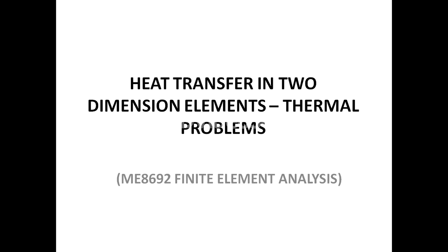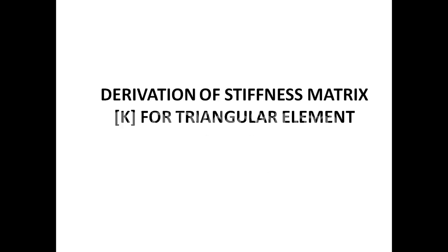Hi. In the previous video, we discussed the derivation of the shape function related to heat transfer in a 2D element. In this second video, we are going to discuss the derivation of the stiffness matrix, that is the K matrix, for the triangular element.